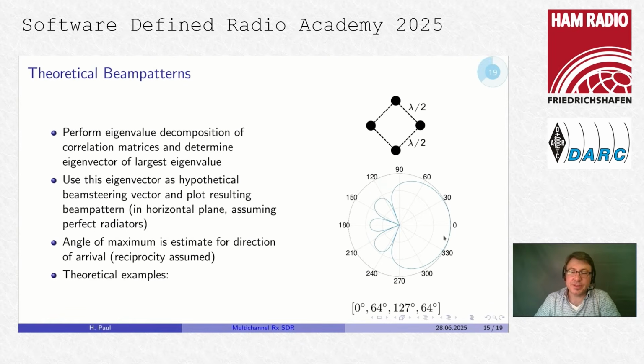And this vector here would actually correspond to this beam pattern here, because for instance, if a wave comes directly from the right, it will detect it first at this antenna. Then after a little delay, it arrives at these two antennas at the same time. And at last, it arrives at this antenna. And it's equally spaced. If this is lambda by 4, sorry for the typo. If we have lambda by 4 spacing here, like in the Foursquare antenna, then you get these resulting phase shifts in the receive signal.